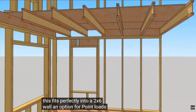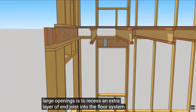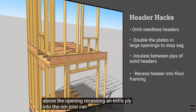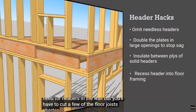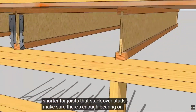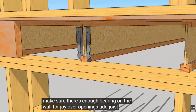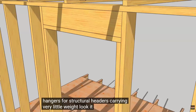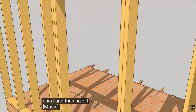An option for point loads over large openings is to recess an extra layer of end joist into the floor system above the opening. Recessing an extra ply into the rim joist can eliminate the need for headers in the wall, but you'll have to cut a few of the floor joists shorter. For joists that stack over studs, make sure there's enough bearing on the wall. For joists over openings, add joist hangers. For structural headers carrying very little weight, look it up in a load chart and then size it right.